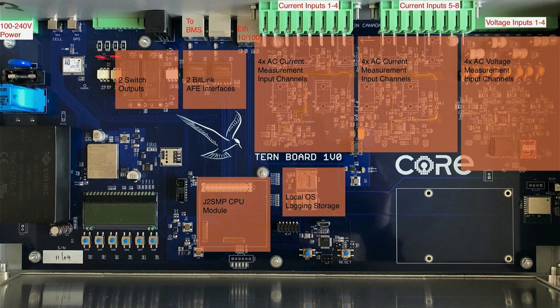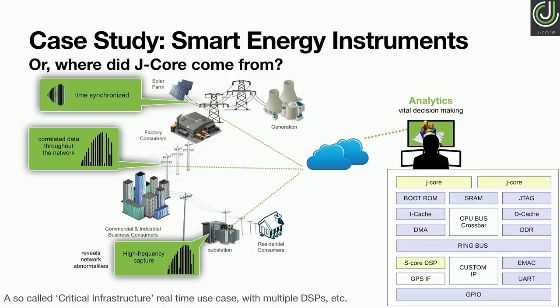Obviously, we're talking about many DSP cores. There's something we call the S-Core DSP. This particular platform has 24 DSP cores on it and a bunch of hardware accelerators. Up here, in each of these analog blocks, there's an ASIC that we did that has a very high resolution delta sigma converter with time synchronization for simultaneous sampling. This is the kind of thing that you can do with open source hardware today. And that's really important. That's why we did this.